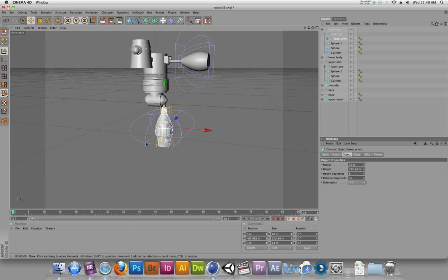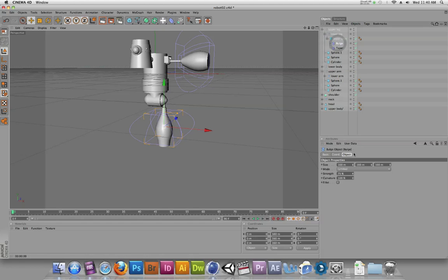And you can see that it's falling outside of those deformations that we applied. So now we've got to go inside and find the bulge and adjust the size of the bulge. We have this bulge bounding box, and it's an XYZ value. If I find the Y value, I could make that taller. Alternatively, I could change the mode of the bulge from limited. I believe if I set that to unlimited, that'll adjust the way that the bulge is affected. Now, it's not exactly what I wanted, so I might undo that, and I'll even undo a little bit more to get it back to its original shape.